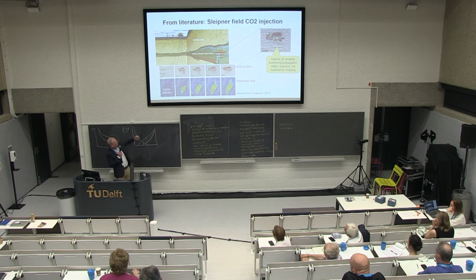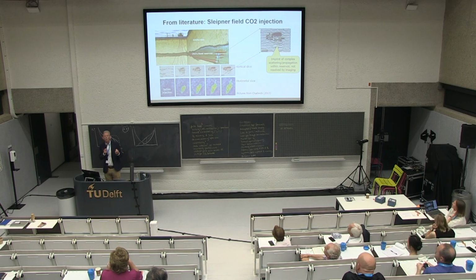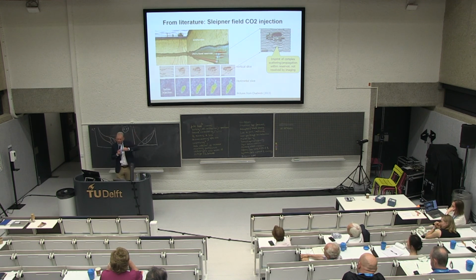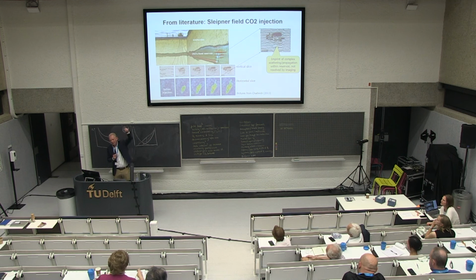But the good thing about this fiber optic cable is you can put it throughout the whole borehole, so you would have free access to measurements all the time over the whole borehole. And in the old days, we had to put a tool in there with geophones, and sink them down step by step, and repeating the measurements is a very expensive process. So by having this installed fiber optic cable, the only thing you need to do is put seismic sources at the surface. That's the only thing you have to do. And then you can just listen to the signals that are received by that cable.